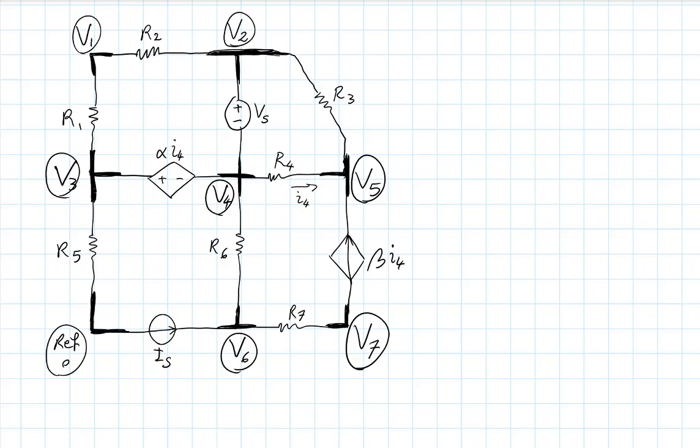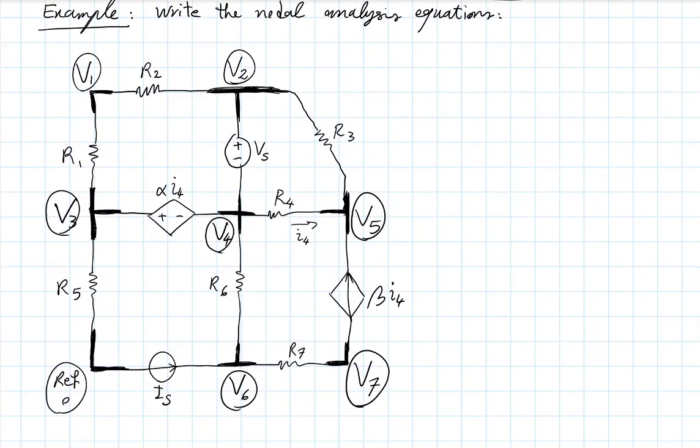Okay, if we now accept that by choosing to work with these well-defined node voltages, we have already implemented our KVLs like we saw last time, we are not going to need to write them explicitly. They are taken care of automatically. And so we are left with KCLs. Let's start doing that and see how far we get. To write KCLs, we need currents, right? So now we have to define currents for each element in each branch.